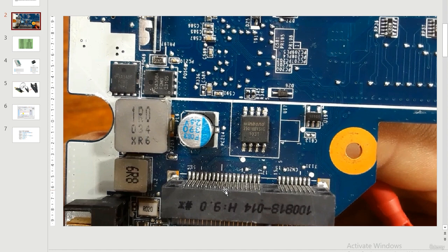All components, all chips seem to be good, with no hot chip. The motherboard is not broken. You check the connectors and find that none are damaged. All voltages are present, but the problem is still here. If the motherboard is dead, it means you should reprogram the BIOS. You have a corrupted file inside the BIOS.